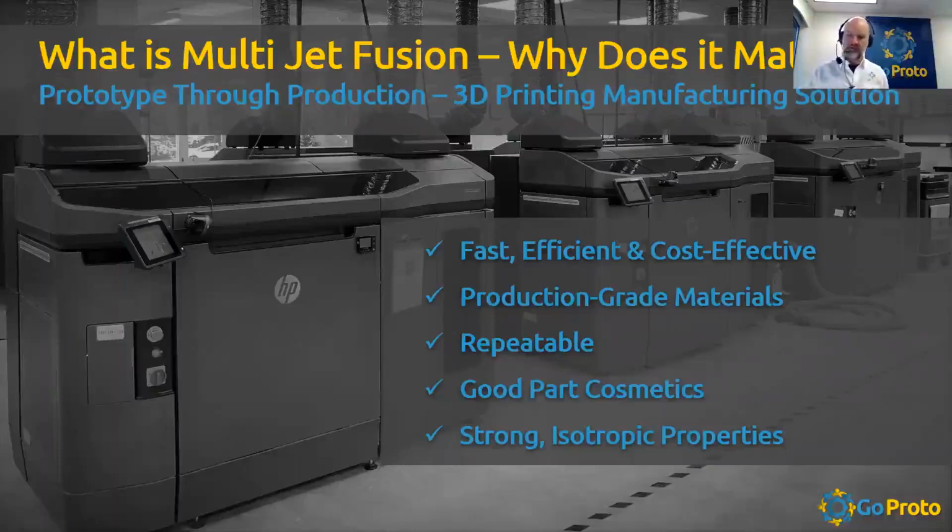And then we talked about being cost effective, being able to nest together well. A big discussion around 3D printing and this process in general, when we talk about design considerations, is that it's important to be thinking about nesting. How are these things going to fit together is important. That's something that usually isn't thought about with injection molding. But if you take apart your design and are clever with the way things can be nested together, then we can incorporate more parts per build. You may have a boss that you use to attach it to another part. Instead of printing it standing up, you can print it with a living hinge in it, folded over so that your Z height is way smaller. Now instead of printing only 5 per build, we can print 10. That kind of little trick can make a massive improvement in your cost.